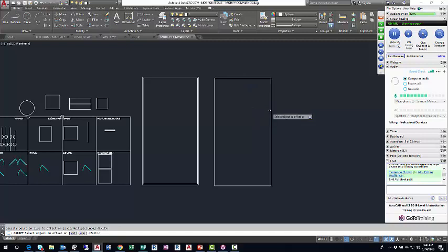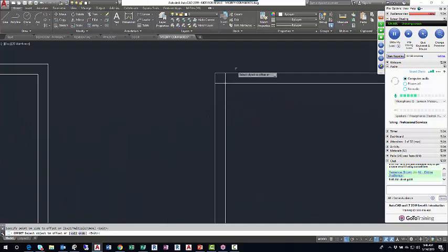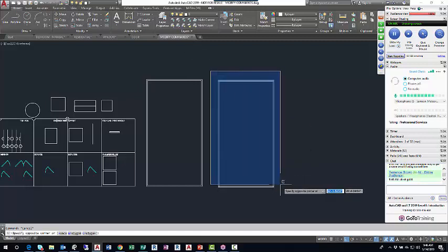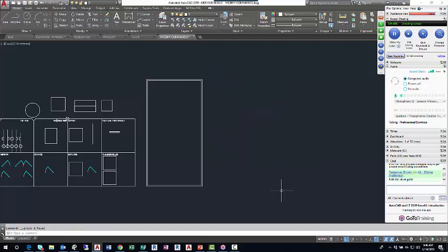Now I'm going to do the other face, or a section, or portion, whatever you want to call it, segment of the rectangle. So it took me 4 clicks, and now I've got to clean up the corners with my trim command. If I know I'm going to create a complex shape, I might use the Polyline command to get there.